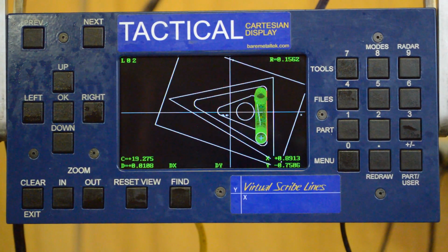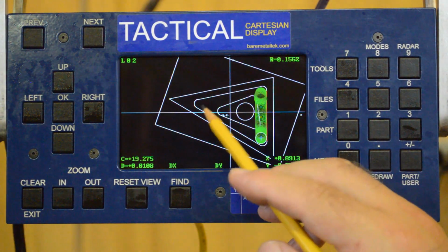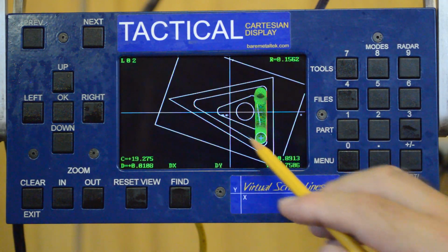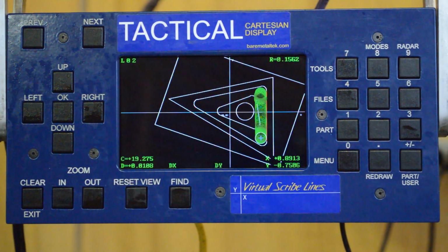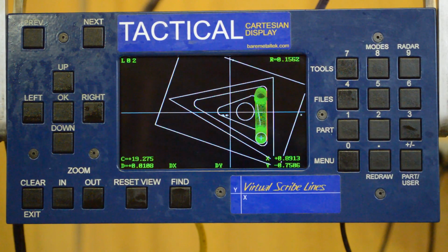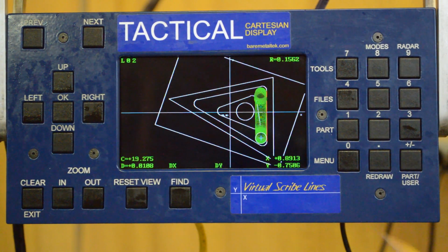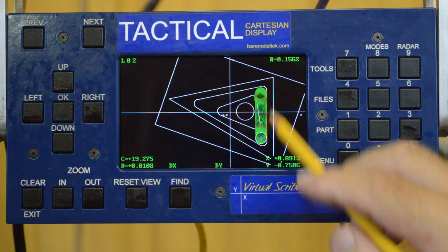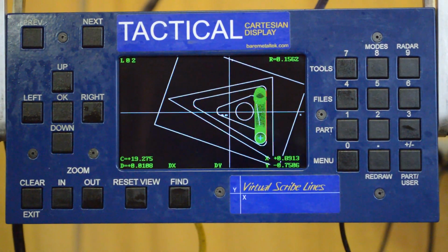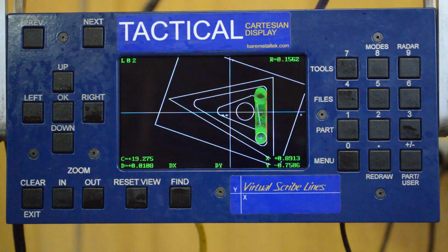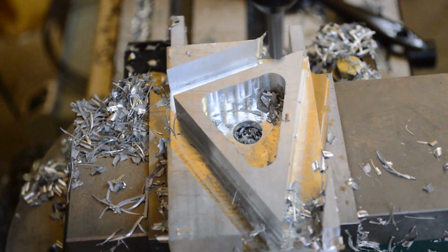Now I'm just going to do the same thing, except I'm going to go to 5/1000ths of an inch. I'm going to leave 5/1000ths of an inch on each wall. I'm just going to climb cut all around, leaving 5/1000ths. And I won't have to be as careful in the corners this time. This operation will leave the part well postured for our finish pass, which is going to be done with a 1/4 inch end mill. These are, I'm sorry, 1/8 inch radiuses. We'll be using a 1/4 inch end mill, and that'll be our final pass. We'll do that next.